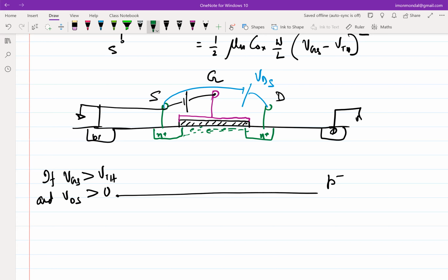So the tap essentially is the VGS, but how much water will flow, or how much current will flow between drain and source, is dependent upon the VDS, right? So the lateral electric field decides how much of the charge will flow between drain and source. Okay, so this is quite simplistic. Now, as it turns out, if you make VDS just equal to VGS minus threshold voltage, something interesting happens. What happens?